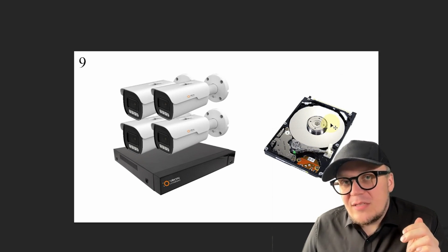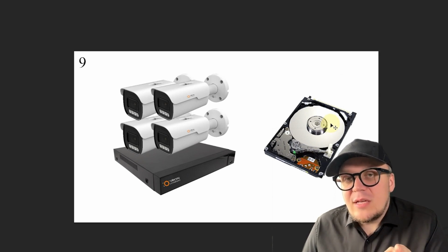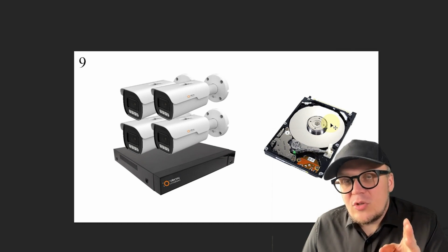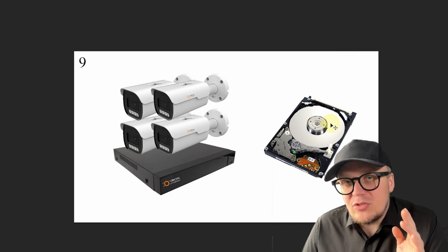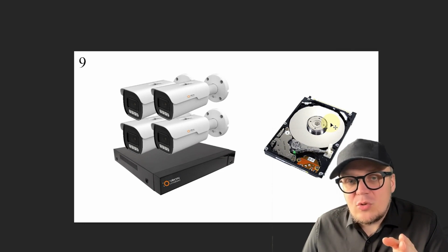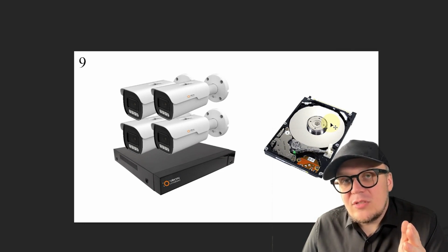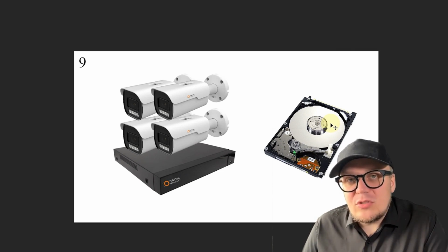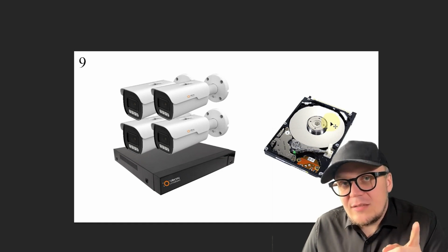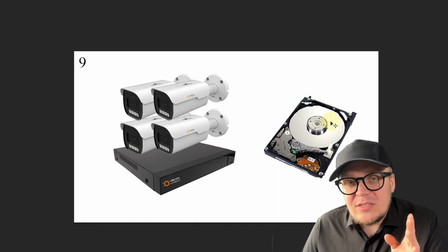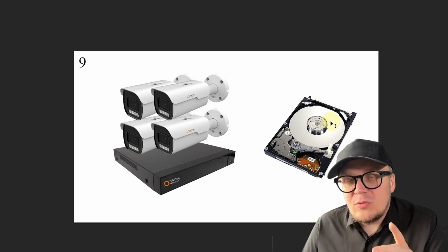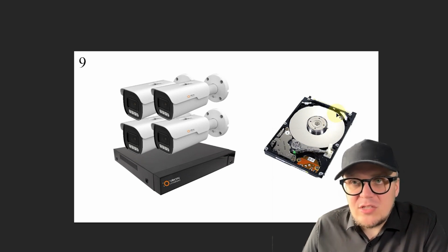And it often happens that a person just installs the hard drive, thinks that recording has started, the recording is going, a few months pass, and then a thief comes during lunch. The person goes to check the recording and it's not there because the hard drive wasn't formatted. Therefore, if you install a hard drive, make sure to format it. If you purchase a ready-made video surveillance system, specifically here with all the ISON models that we have already reviewed, models with a hard drive, there is no such hassle. It is already formatted and ready to work.